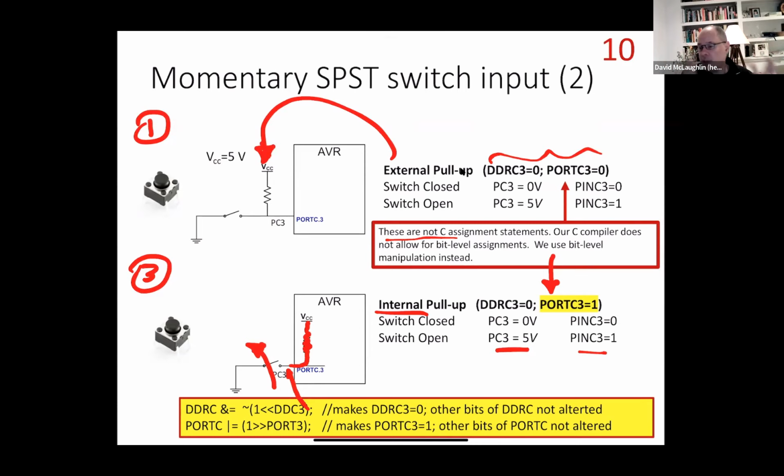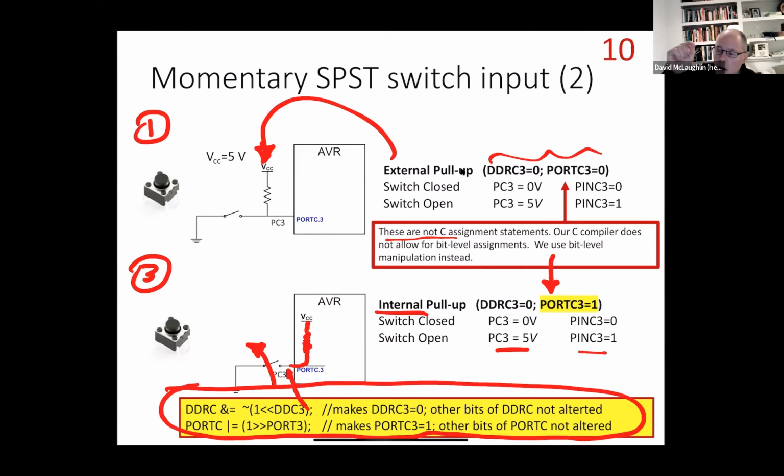If we were writing in assembly language, we could actually go in and target the individual bits. And so because of that, we use the kind of fancy constructs that we've been looking at, where we want to go in and surgically target one bit, set it high or low, even knowing we have to simultaneously do something with all the bits. And so that's why we were using these funky kinds of commands that we've been creating, the AND equals and the OR equals, which we just looked at previously.